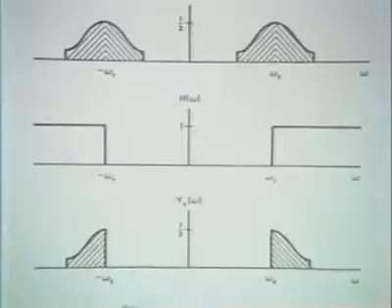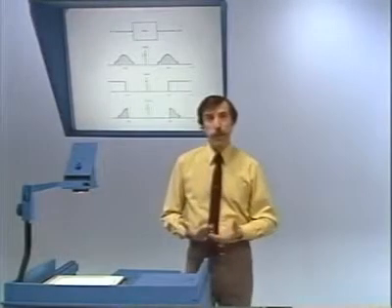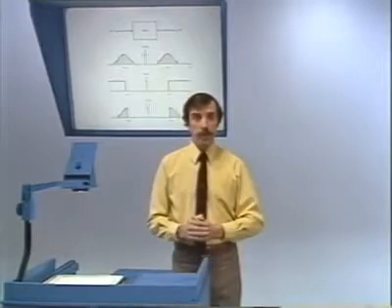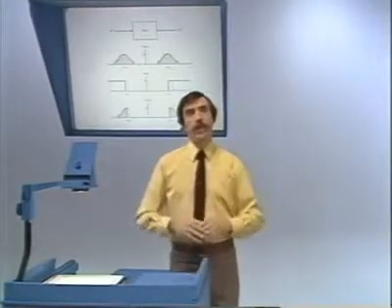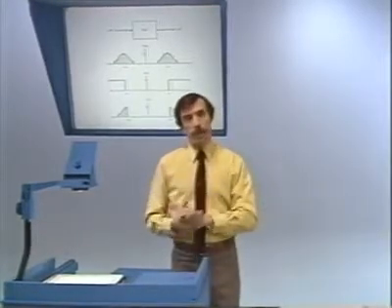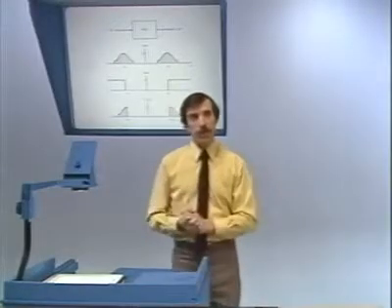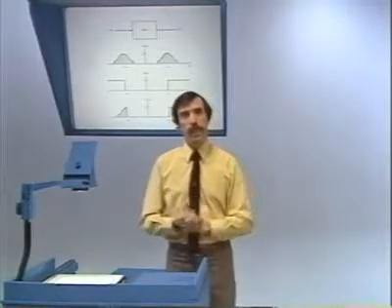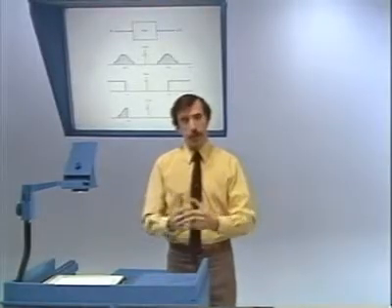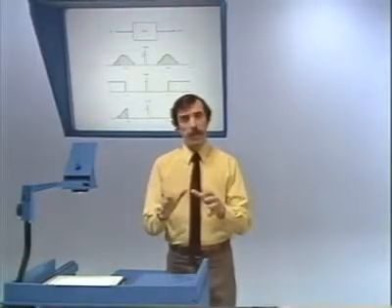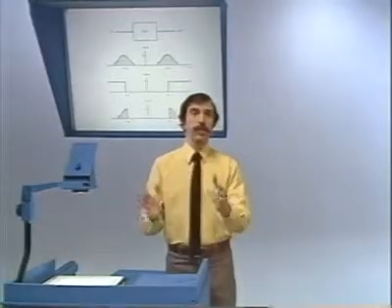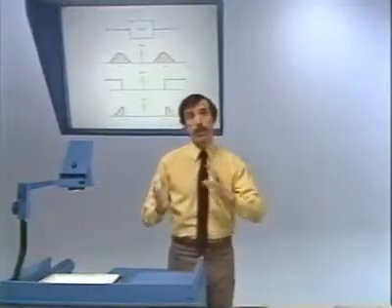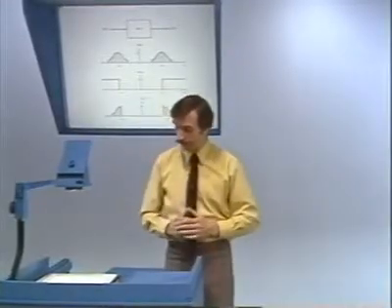And this, in fact, is really the basic idea behind single sideband transmission. Again, there's a trade-off. It's clearly more efficient than double sideband transmission, but it also has the complication or additional issue that the modulator becomes a little more complicated, because you need this filtering operation or some equivalent operation to get rid of the unwanted sideband.